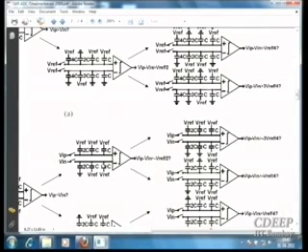Now come to the lower one. So what is the upper side? Untouched, 0. What is the lower side? Vref by 2. That is the reason they are using a smaller number of capacitors. So they are achieving the same thing but with fewer capacitors, and less switching and less power dissipation.